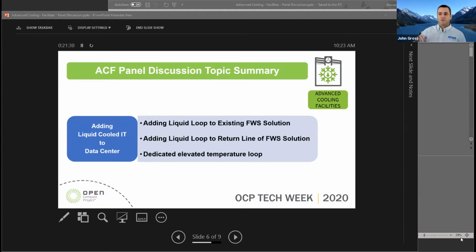So it's 17C water. As part of that conversation, I was actually educated on where the current numbers actually came from. And the W1 at 17C was originally developed because the thought was that anything below that was potentially below dew point, and anything above that was potentially above dew point. 32C was picked for W3 because that seemed to be a reasonable break point for evaporative cooling versus not. 45C for W4 was heat reclaim.